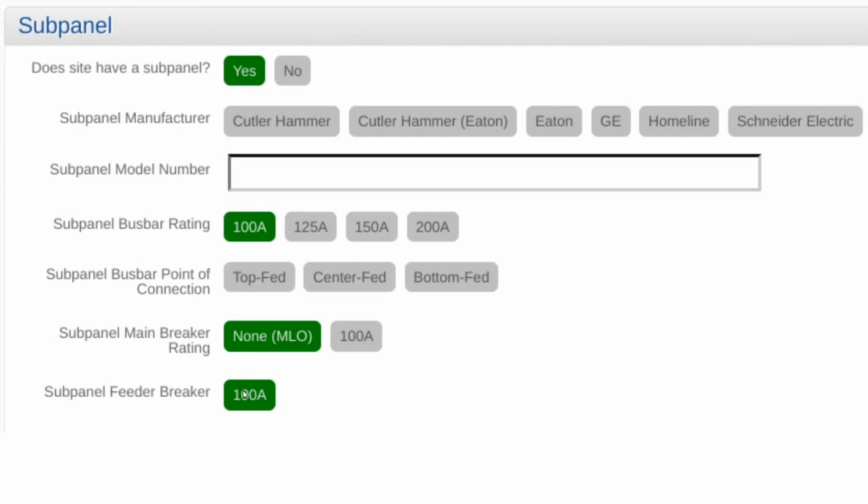Here, Solar Design Tool is asking for subpanel information. A subpanel might be used if there are multiple inverters which need to be tied into a single point at the main service panel. While Solar Design Tool has many different configuration options, it may not have the exact configuration for a particular job site. So in many cases, it will generate a permit-ready document, but sometimes minor changes are necessary to be completed in an external CAD software such as AutoCAD or DraftSite.